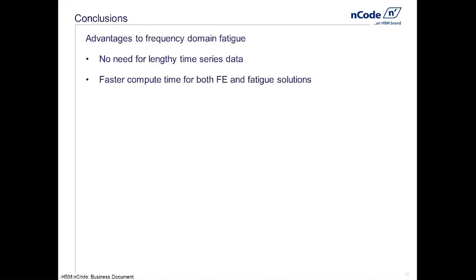Another nice thing is we weren't accounting for dynamics and resonance here. So if your FE model is set up appropriately, and if you can understand the role of damping in that, then we'll be able to understand dynamic response and resonance and such, which is great, because now as an engineer, you can check the box that says, okay, did your fatigue analysis account for resonance or not? Because I think resonance is going to be a problem. So this way we can account for resonance.